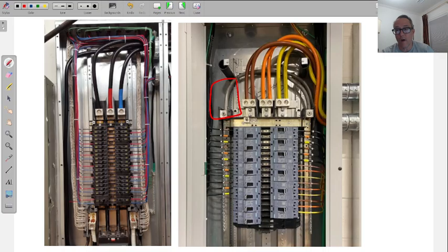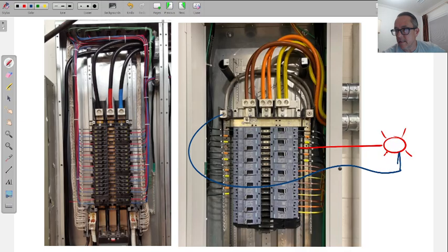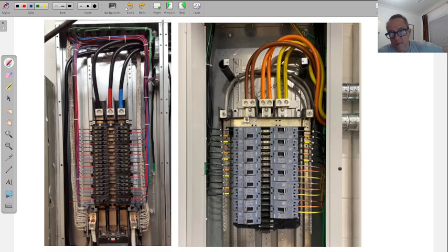So it is good to know that's a Y, because if I need to run an outlet, I wouldn't set up a standard electrical outlet because I can't set that up at 277. I mean, I can for some machinery, but I can set up a lighting circuit. All right, I can put some lights here because I got a neutral that I can send to this light. So this panel here would be a very good panel for commercial or industrial building lighting systems.